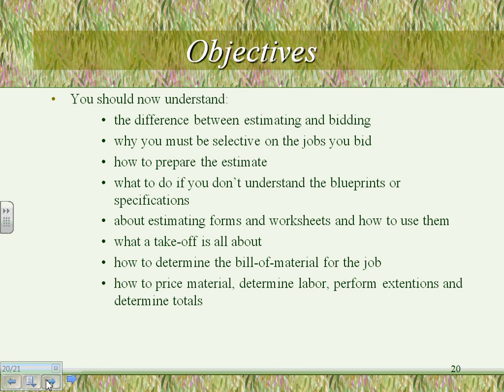No devices, none. If you look under receptacles, the convenient receptacles, I have 9 of them. I have 9 4x4 boxes for them. EMT conduit, 18 feet of it. I need mud rings, one gang, 9 of them. And I have devices. The device itself, I have 9, and plates, 9. Can you guys see that?